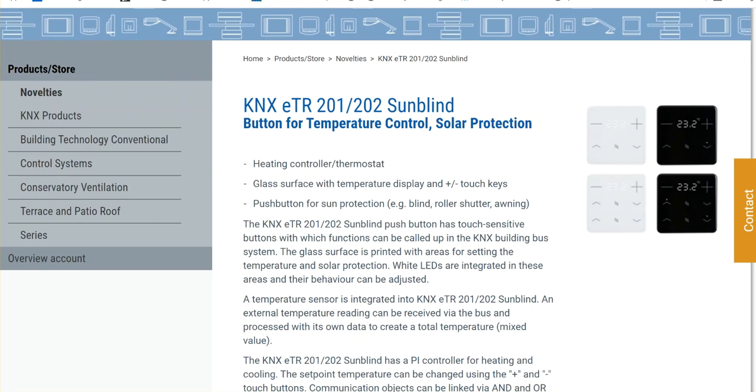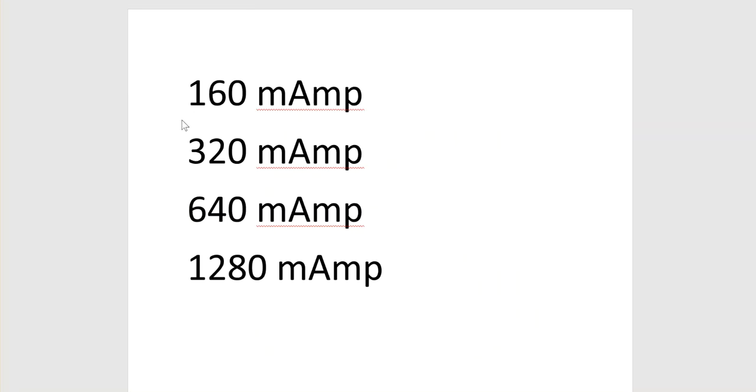Yeah. So, for example, if you want to choose these power supply units, always try to have at least 20 to 30% more power here. I mean, when you want to select, if you have 10 devices with each one consuming 10 milliamp, you consider this one.